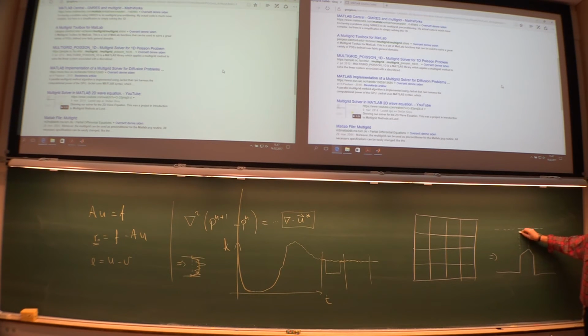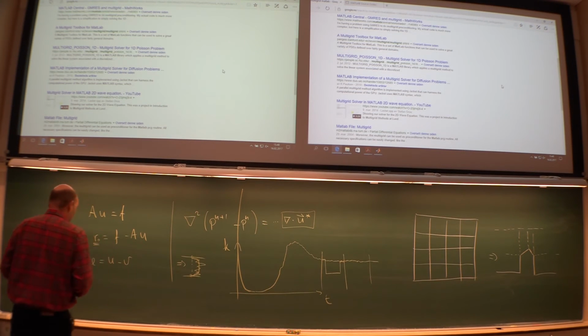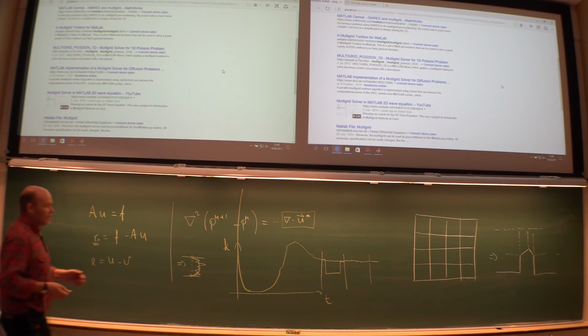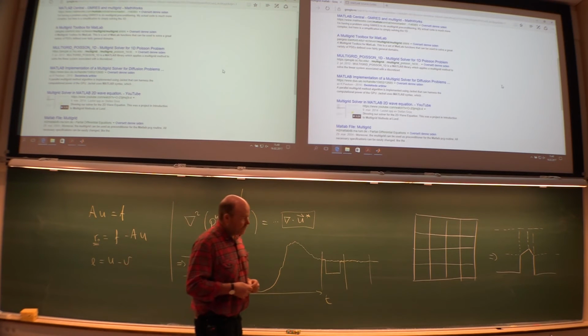Typically what people do here, they split it up into blocks, maybe something like this, and use separate multigrid algorithms for each block. Tricky, then the blocks have to talk to each other, but you have to do something here, because the coarsest mesh, if you have complex geometry, can't really be covered. And you also have the problem that on the coarse mesh systems you need boundary conditions on every level. Remember, the equation system is elliptic, so you need boundary conditions all around, also on coarse meshes.